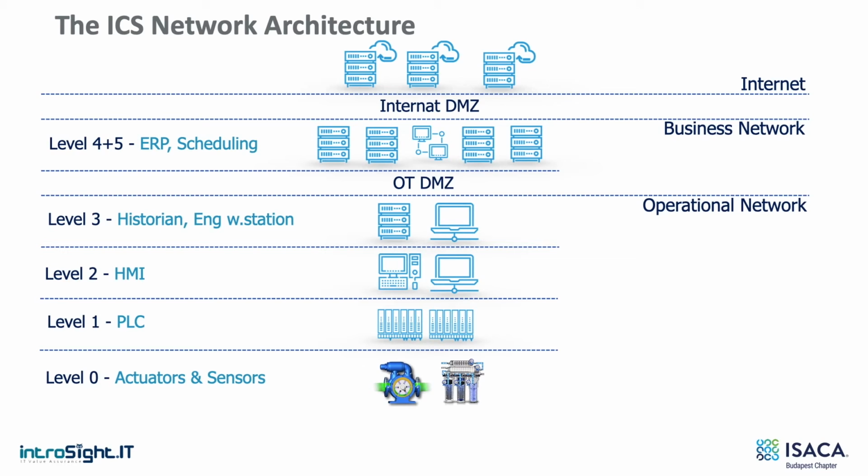Back in the day, OT networks were truly isolated and used proprietary and unsecured protocols, which are not routable over the internet. Today, almost every ICS network is connected to the IT network, and proprietary protocols are encapsulated into TCP, thus allowing them to be routable and accessible from the internet. When we started looking into network architectures during the project that we conducted, we realized that connectivity between the OT and the IT network is not built on security best practices and introduces a significant attack vector on ICS. Let's see how network architecture might look if the CISO were to apply security best practices to ICS networks.